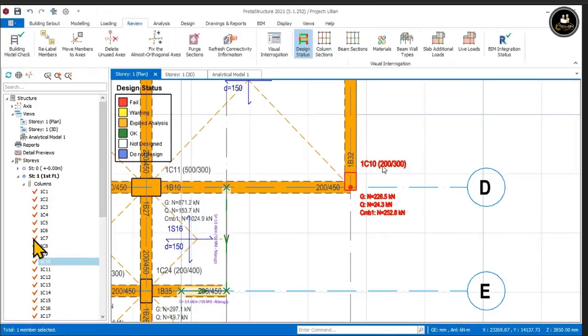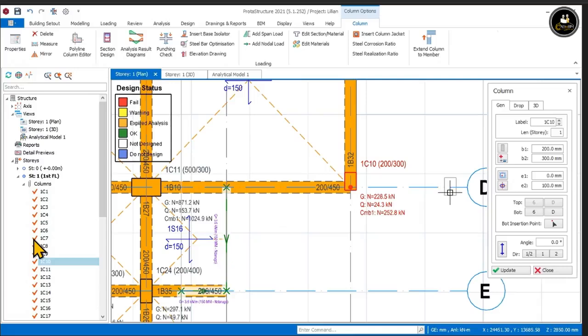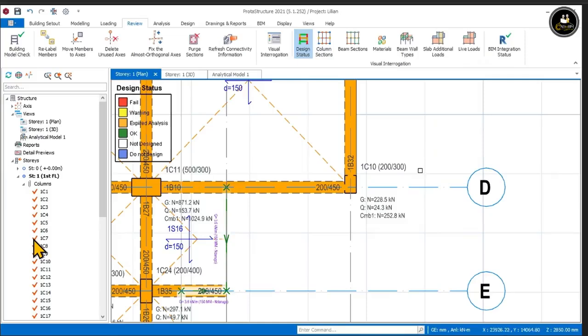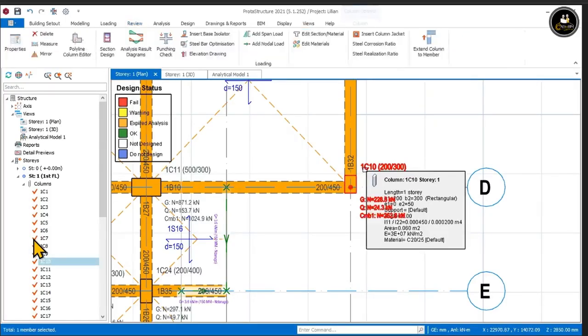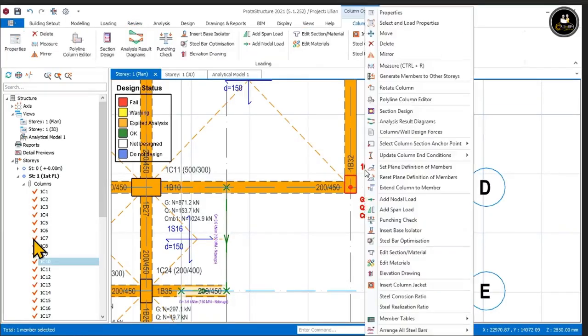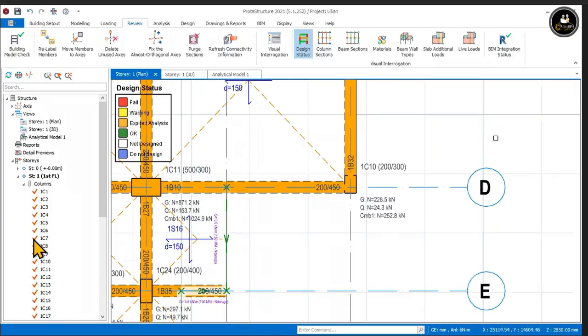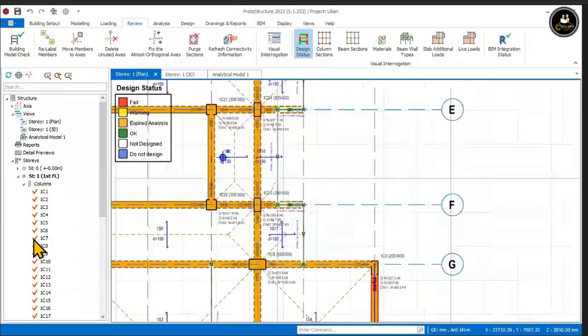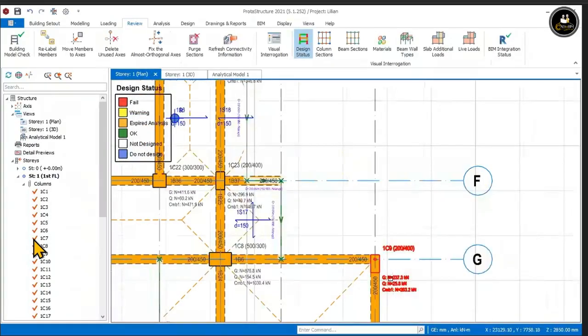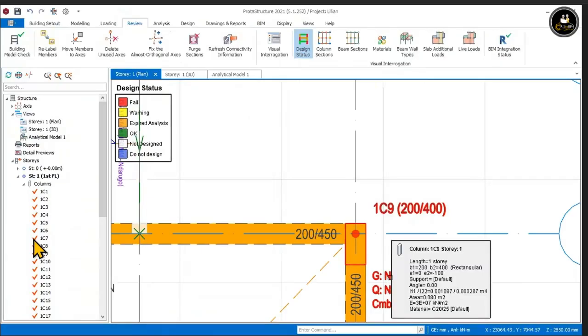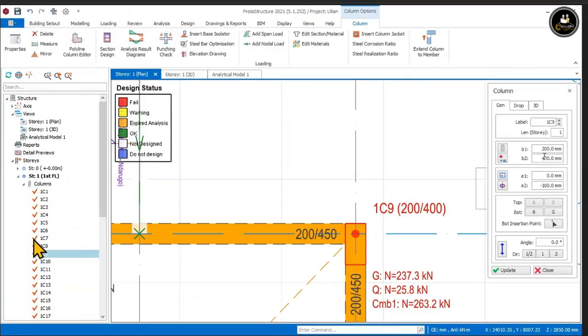So you should also check on the eccentricity. Maybe now you can make it 50 instead of 100. Yes, that will still be fine. Let's also change the opposite, the twin sister of that column. This one. Yes, that one. Put it 300.